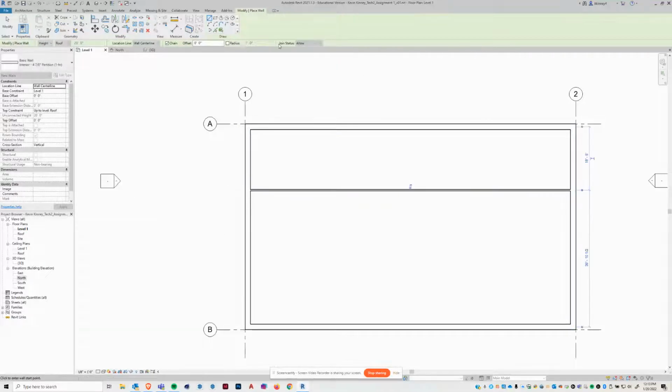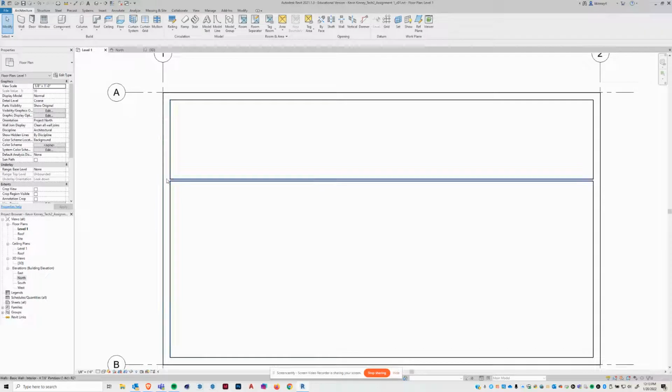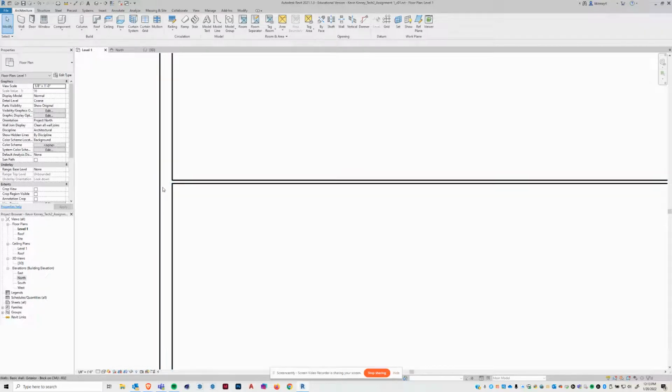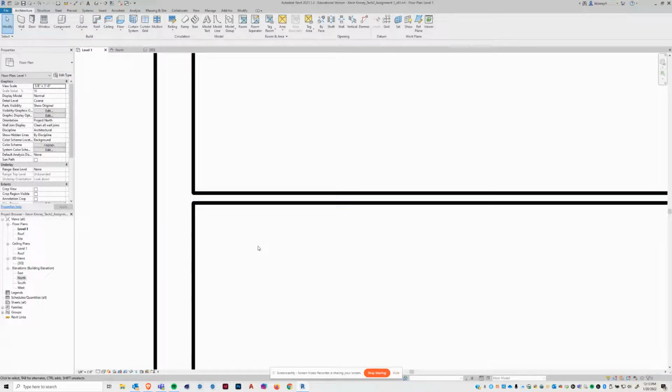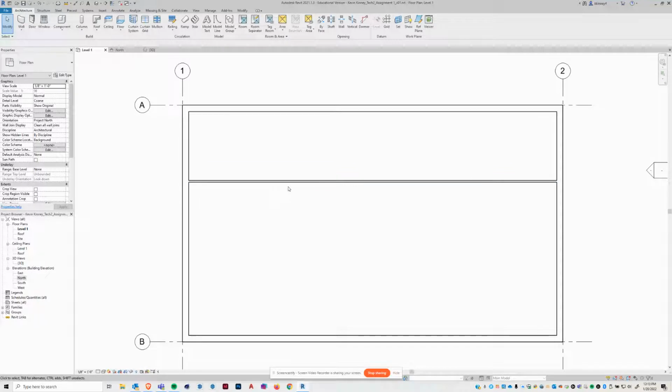There we go. Okay. Now, I select that wall. I can double check that it's going from level 1 up to roof. It's doing exactly what I want it to do. Notice that when I started from over here, it just sort of blends in right away and it draws our floor plan correctly, which is very, very nice. All right, so let's draw. Now, I don't care where this wall is at the moment. Okay, we'll get to that.